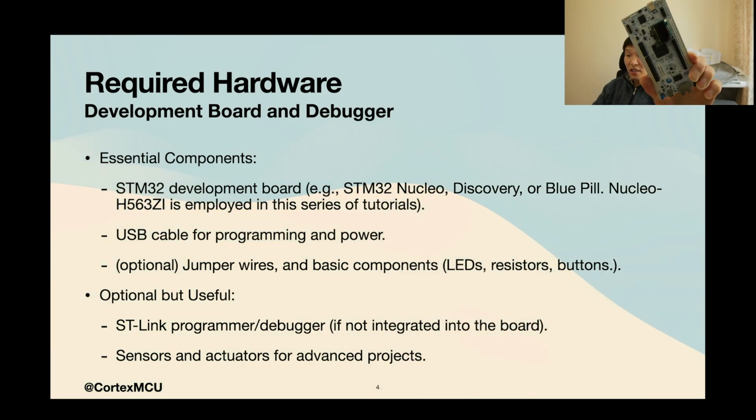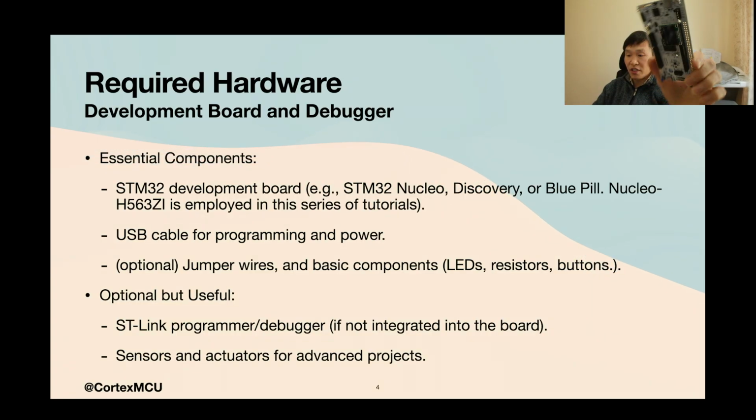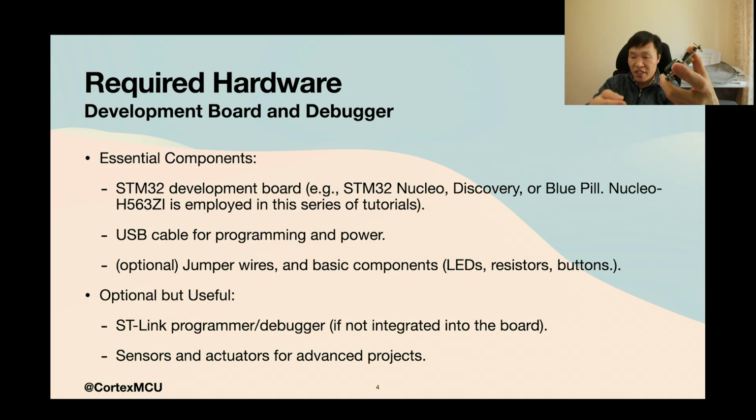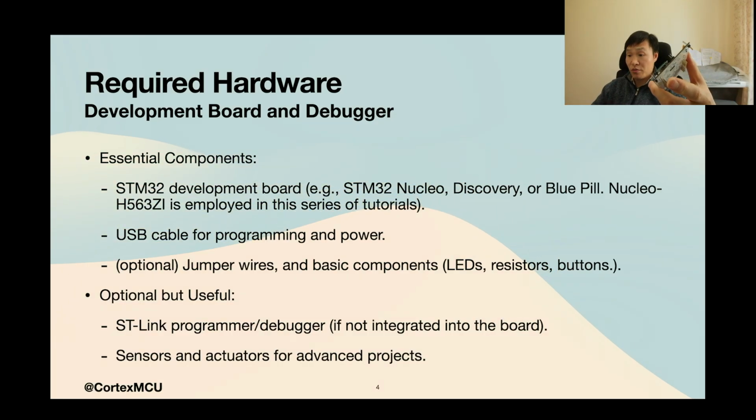We just connect the USB cable into the USB Type-C connector. We are able to program and debug the firmware with the cable. So we don't need to buy another ST-Link programmer debugger device.